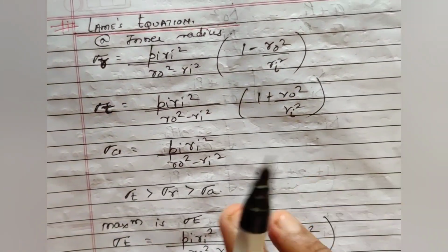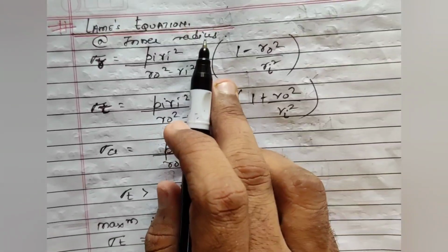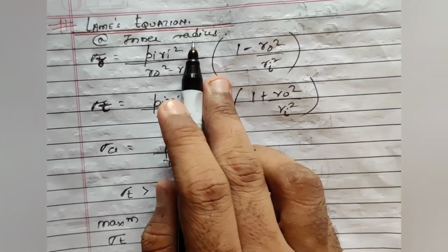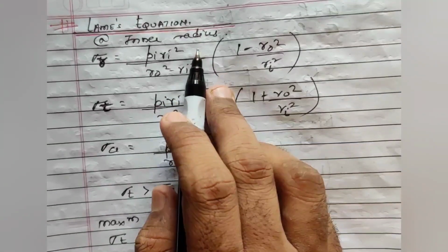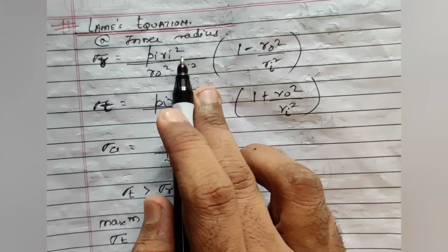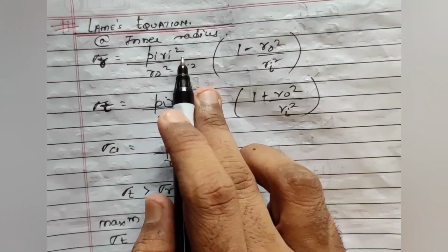This was your radial stress equation in terms of R. And axial stress was constant. So those equations we are rewriting here, on the inner radius, because the inner radius was the critical point. What the maximum normal stress theory states is that your component will fail when the maximum normal stress exceeds the normal stress of the material at the yield point, when the yielding starts.